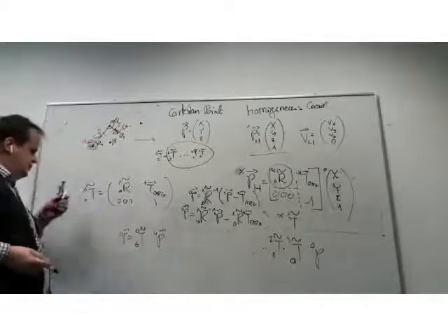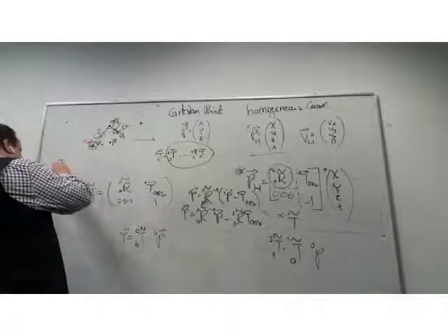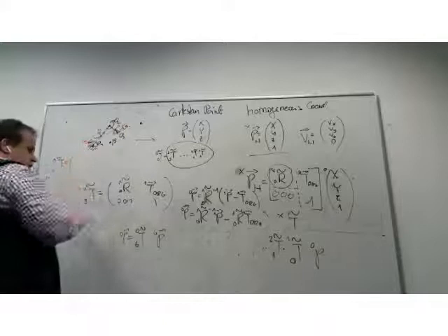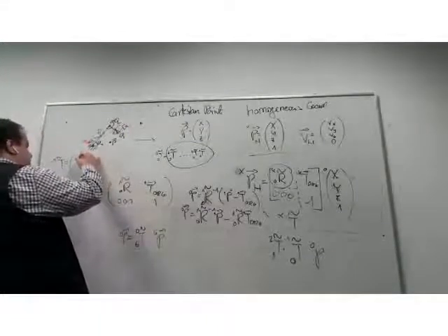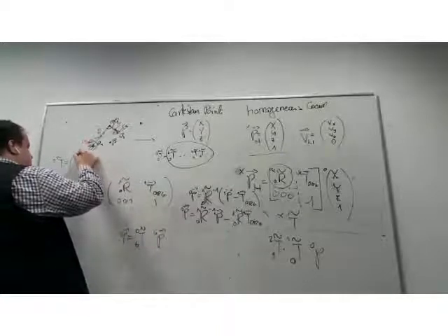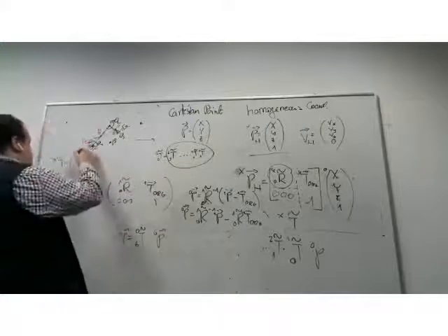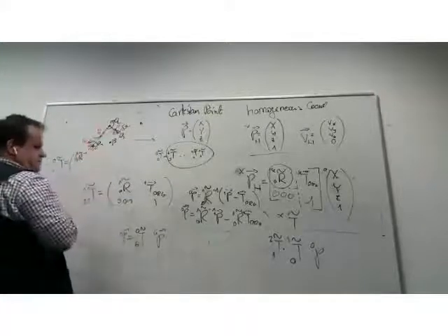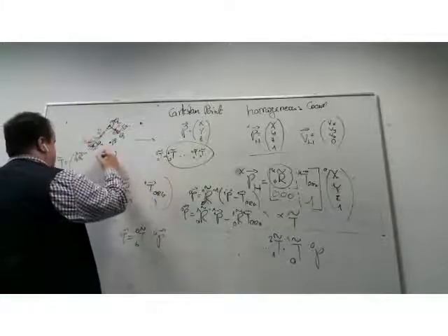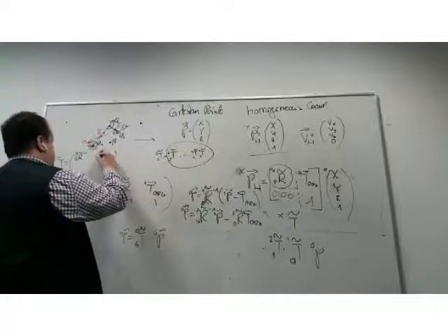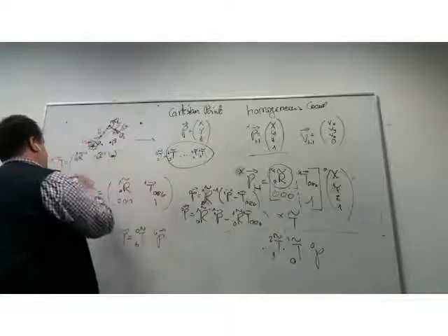If I know from 0 to 1, how do I build the inverse from 1 to 0? Well, it's actually already here. You see that I need to get the inverse matrix 1, 0, which is R 0, 1 inverse. My translation vector will now be minus R 0, 1 inverse times P origin.